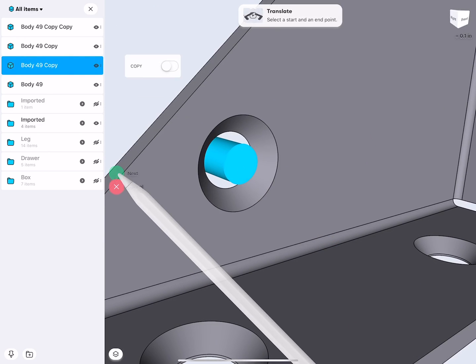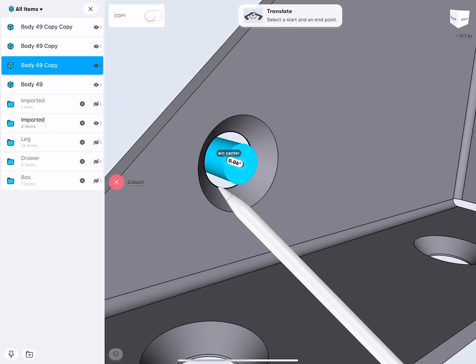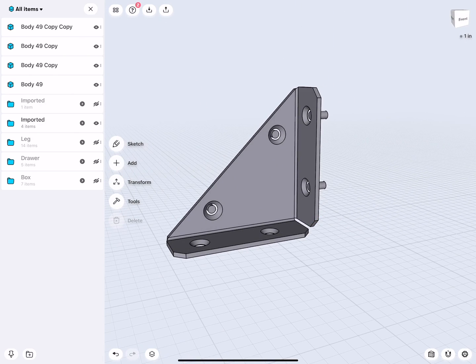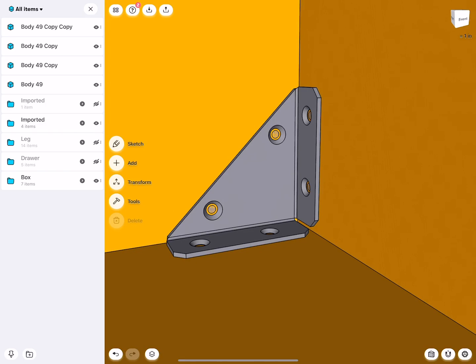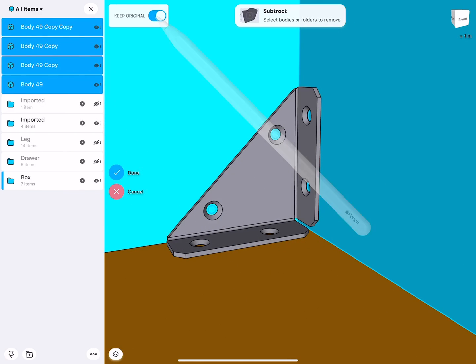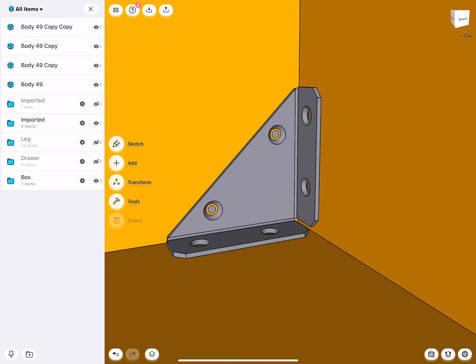There was a little bit of an interface overlay. There, cool. Now, pretty easy, as you see. And again, the reason why I'm creating these cylinders is they essentially function as a hole tool. I could either project those onto a sketch, or I can, when I bring back my box, go tools, and then subtract and say U and U minus these holes. Click done. See, I also again here keep my hole.